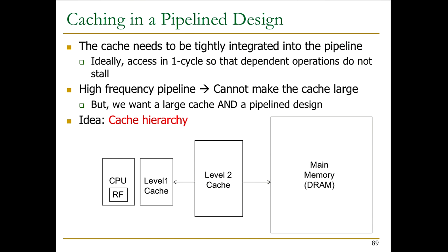So this is the real reason why level 2 caches were introduced, actually, because level 1 caches are too tightly coupled with the pipeline design. They're really there to supply the instruction that's executing at that moment. As a result, you cannot make it large. There's actually another reason why we cannot make it large. It's tied to the virtual memory, and we'll talk about that. Or it's tied to a particular design of the virtual memory.